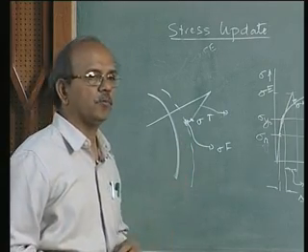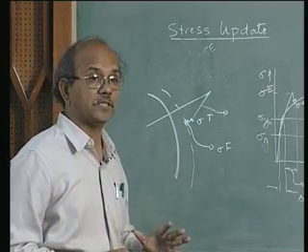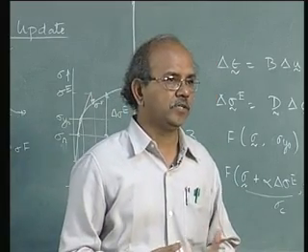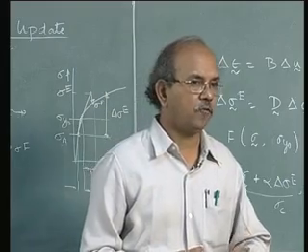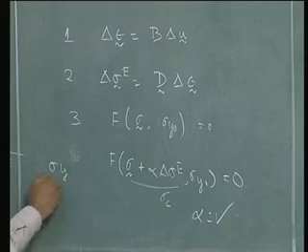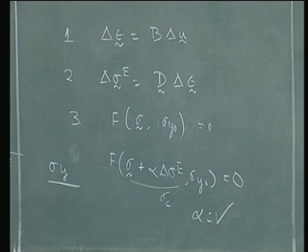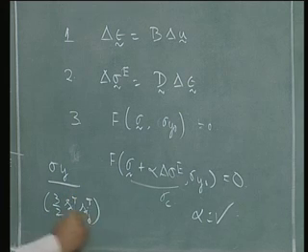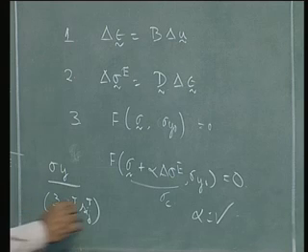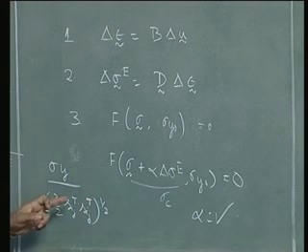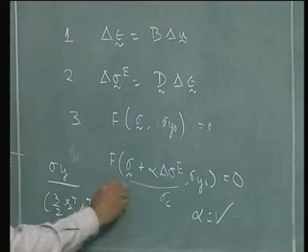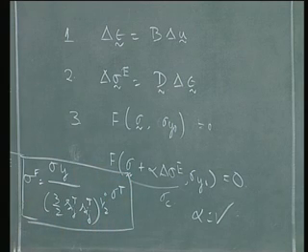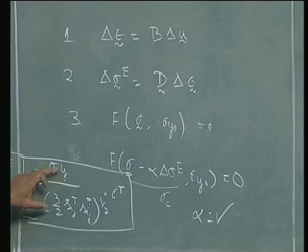Now how am I going to pull back? When I pull back, it should be such that my yield criterion is completely satisfied. What I do is to have a ratio of sigma y divided by three by two Sij t, whole power half, and then multiply with my sigma t, which equals sigma final. Look at this equation carefully. So I use a ratio to pull this back.